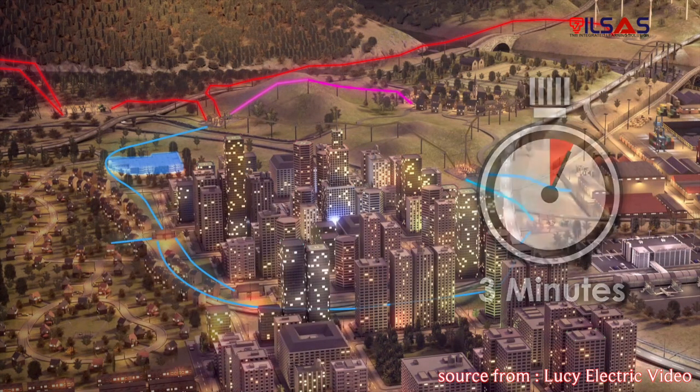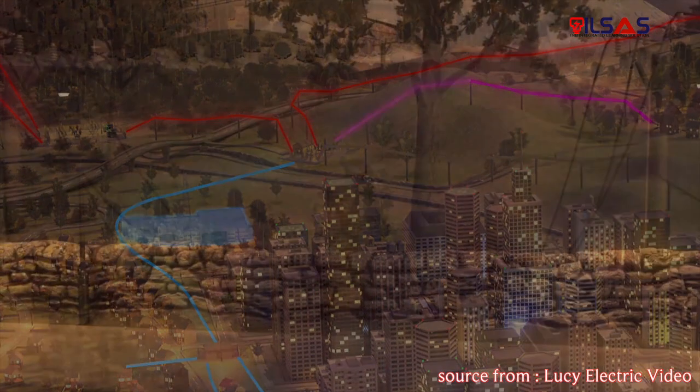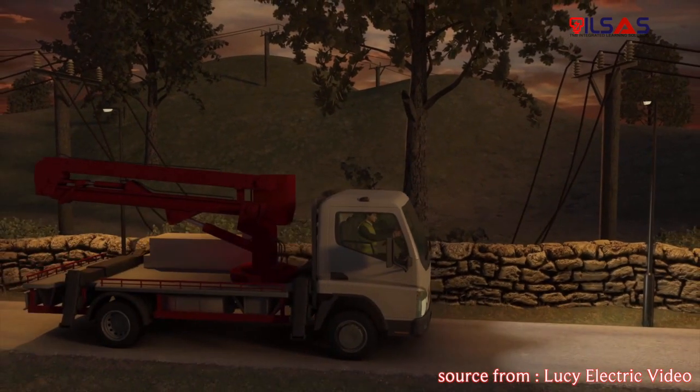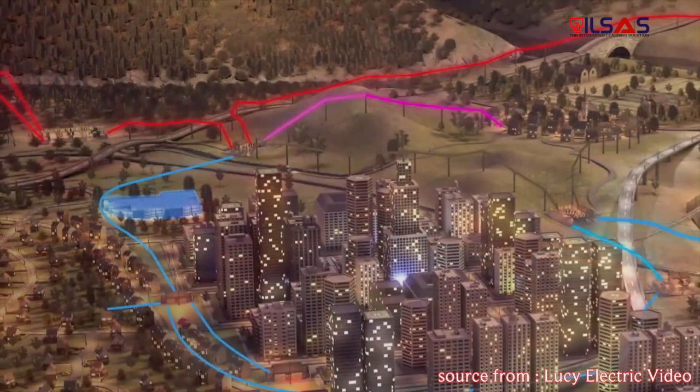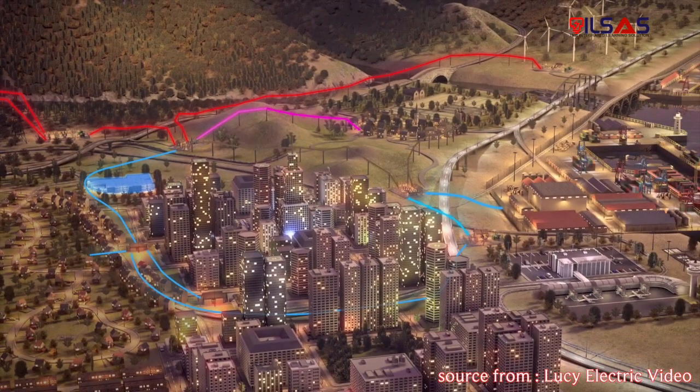Scada enables the operator to direct the repair team to the specific area of the network at which a fault has occurred. Once the operator has confirmation that the repair is complete and all maintenance crews are clear of the area, Scada can be used to restore the system to its usual operation. The newly repaired line is tested first by closing the primary substation's outgoing switch to substation 2. The line energizes as normal, confirming the repair.